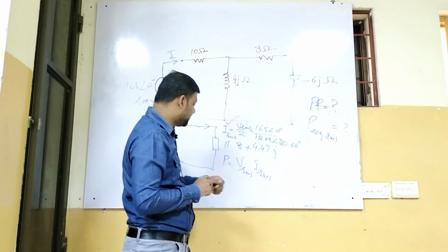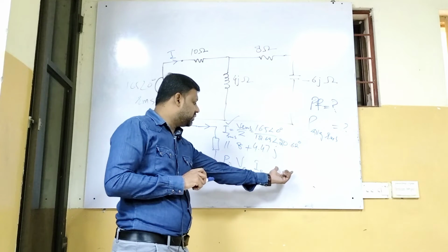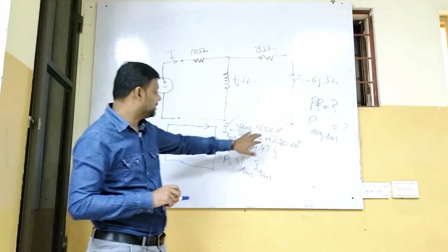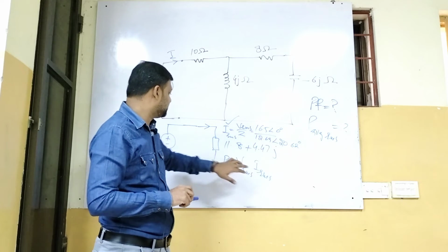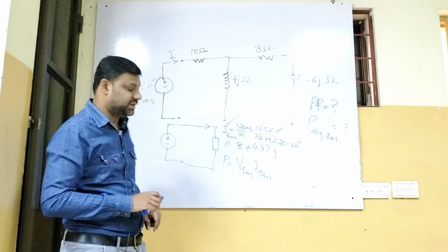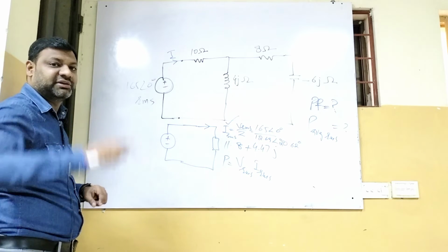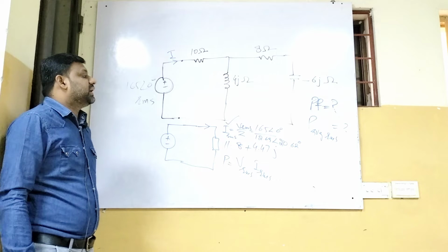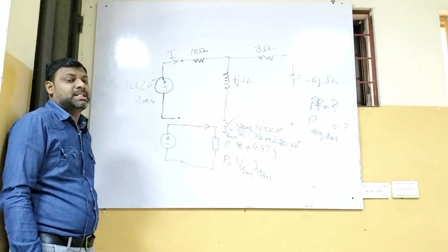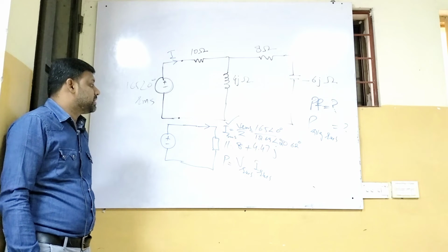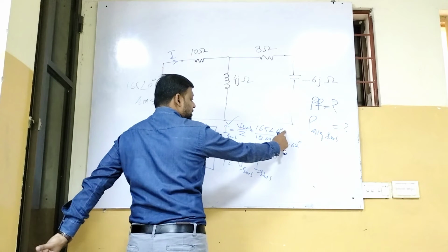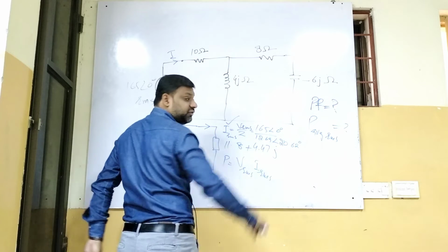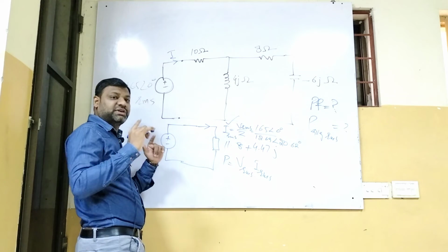He is interested in average power, so we will have the cosine of this angle, the voltage, and the answer. So what about the power factor? Who could find out the power factor? The phase of voltage minus the phase of current, and then take the cosine of that.